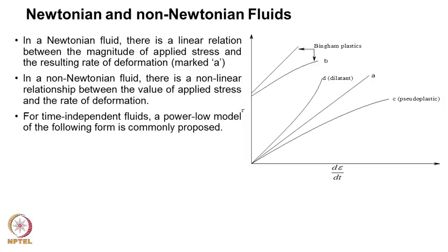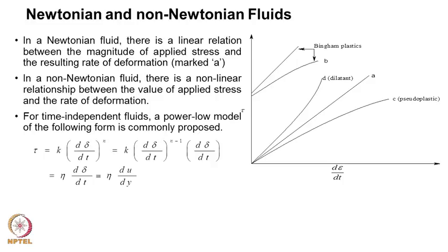Whenever you have a non-Newtonian fluid, there are different models available to describe them. The popularly used one is the power law model, where the stress is related to the rate of deformation by a power law, so it is d/dt of strain to the power of n. The n is the index of the power, and you can separate it as d/dt of delta to the power of n minus 1, and the remaining part is written separately.